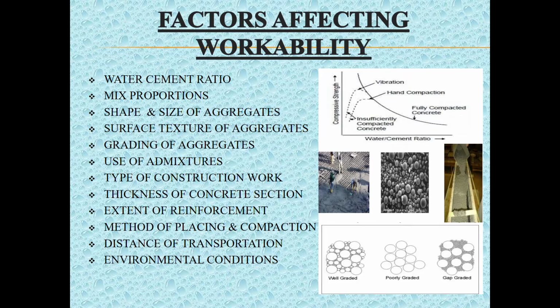When the aggregates are of bigger size and rounded shape with smooth texture, there is less surface area and fewer voids. Hence, less water and paste is required for lubricating the surface, which provides greater workability and reduces frictional resistance. When coming to the factor of grading of aggregates, the better the grading, the less is the void content, which leaves excess paste available to give a better lubricating effect, which in turn gives higher workability. Use of chemical admixtures and air entraining agents also increases workability.